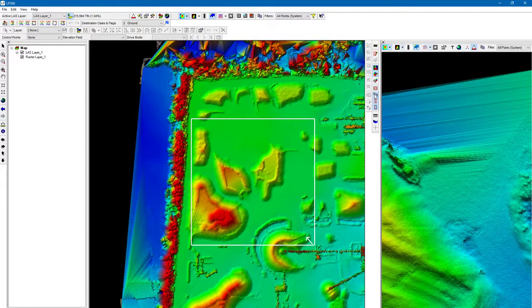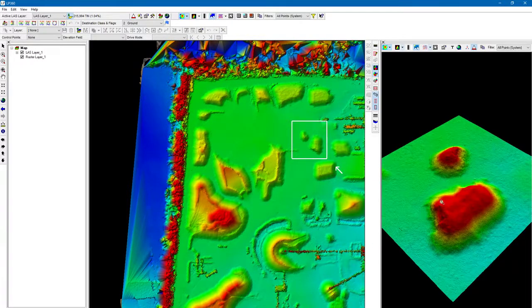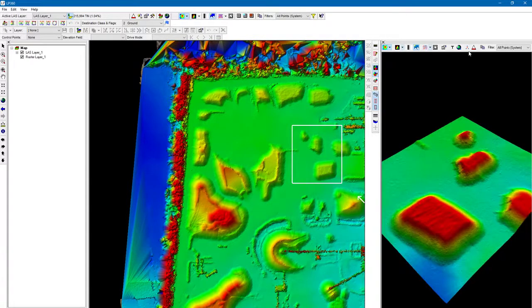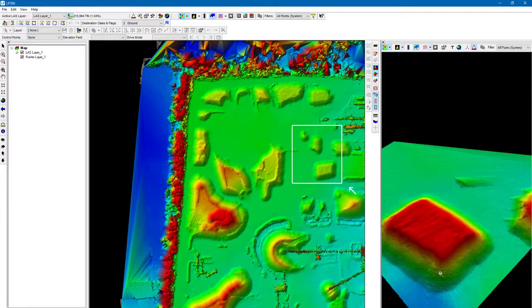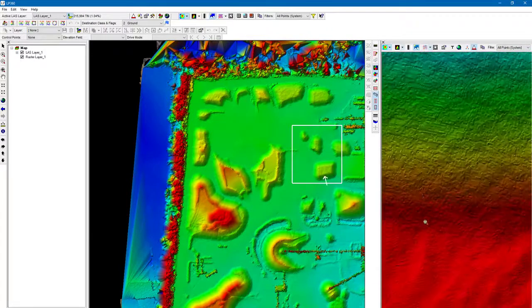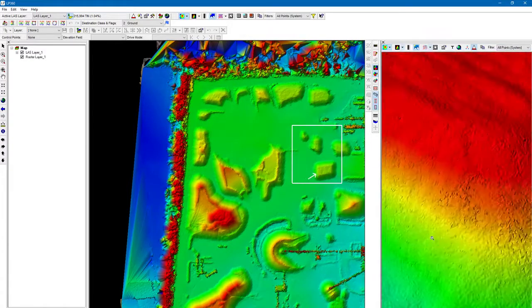Let's go ahead and I'm going to click on draw the 3D viewer extent. We're going to pick a really small area because I haven't changed any of the display settings. You can see I've turned off force 100%. Just make it just a little bit bigger. Okay, let's force 100%. You can see the density of the points if you force 100%. Also, if you just pick a really small area of the point cloud to look at, it's probably going to be displayed at 100%.